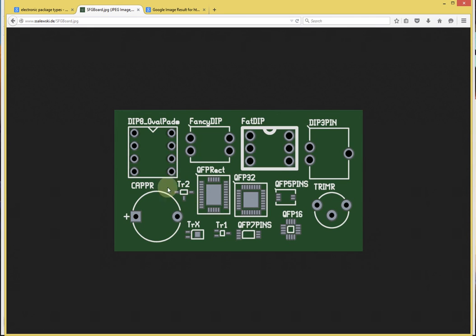That means that they only sit on one side of the board, and therefore you don't need through-hole pads, but you need pads nonetheless where the part is going to sit when it's soldered onto the board. So the footprint itself is composed of any number of pads. For this particular part I'm highlighting, all of these squares are pads that are part of the component. So we have a footprint, and the footprint is composed of one or more pads.